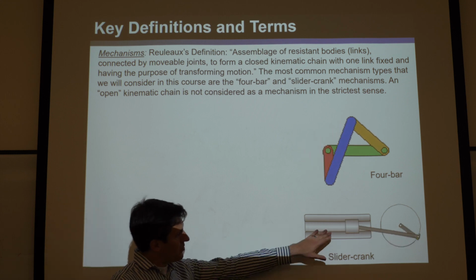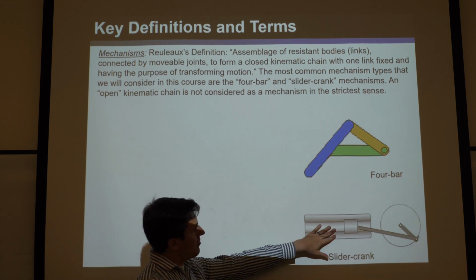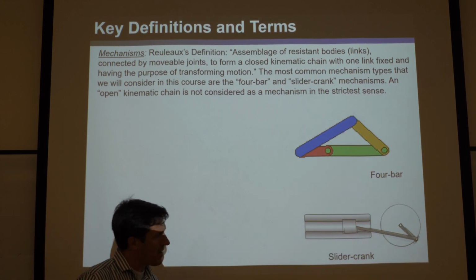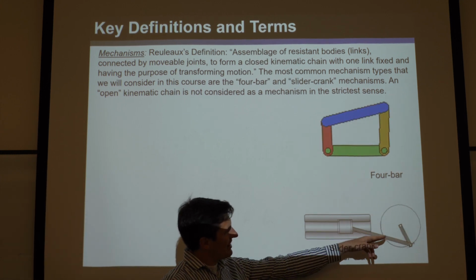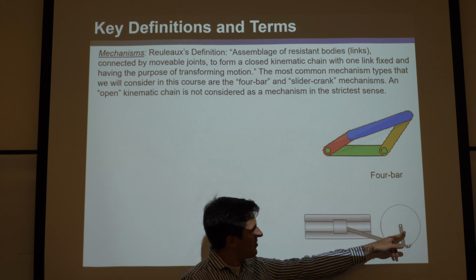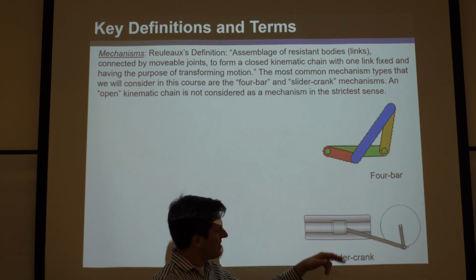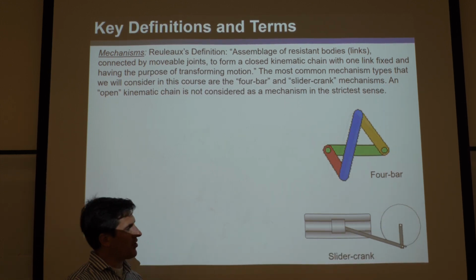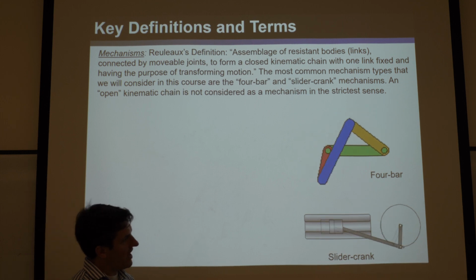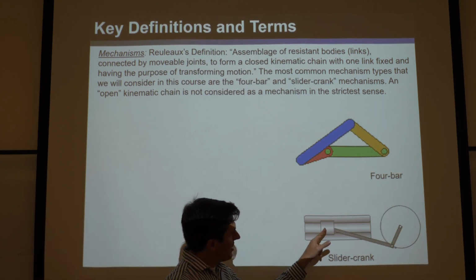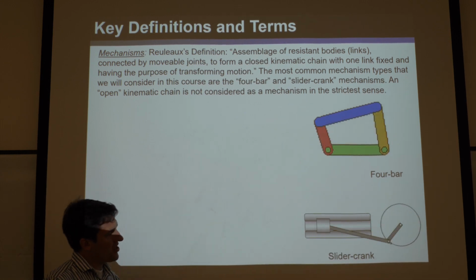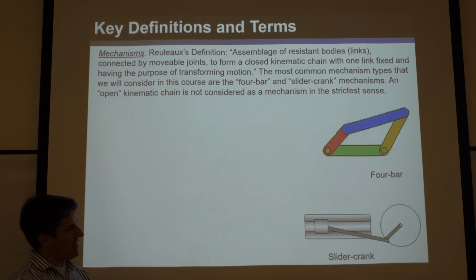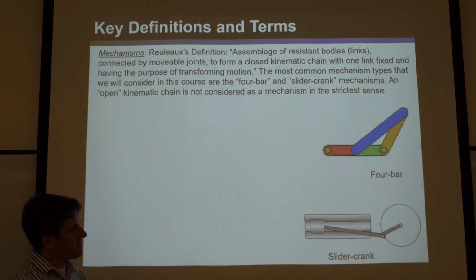So this one is also famous. We've talked about the 4-bar, but this is a slider crank mechanism. And of course it consists of rigid links. You can see here there's the ground, there's these 2 bars, and there's this piston that pushes through a prism or translation joint. And you can see there's a rotational or a pin joint at the two parts there. And so you might say, well, is this a mechanism? Well, it certainly is. It's one of the most famous mechanisms.